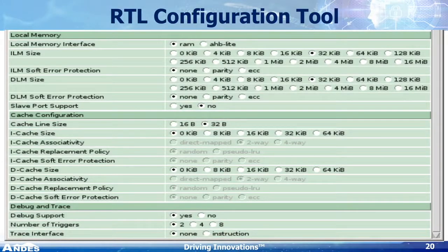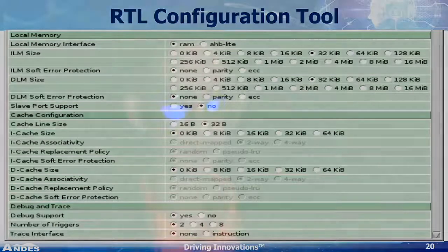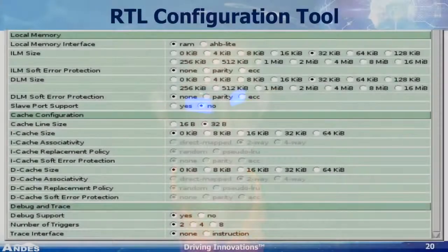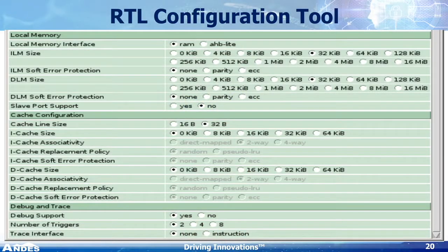So this is a lot of things we talked about earlier. So you can, for example, select whether you want the A instruction or not, atomic instruction. A lot of privilege mode features are optional, so you can select that. Performance monitor, or a couple features that the N is extended. In the bus type, you can select AHB, AXI, 32-bit, 64-bit, and multiplier, branch prediction. And this is for local memory, and caches, and debugging support. So very easy. You just select what you want, and then you have your RTL configured. So it's going to generate a header file for you, and then you can use that to build your simulation and synthesis and so on.